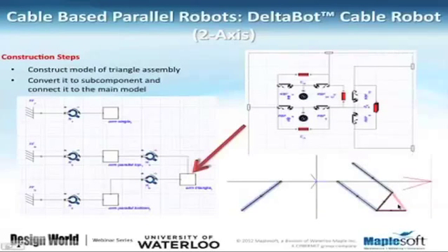So you see in this figure that we have two masses for these two arms, and then we have revolute joints, and these red items are just showing the look of those arms. And then we have rigid body frames, and the rigid body frames are those that are showing the connection between the triangle frame to the revolute joints and then to the other arms.